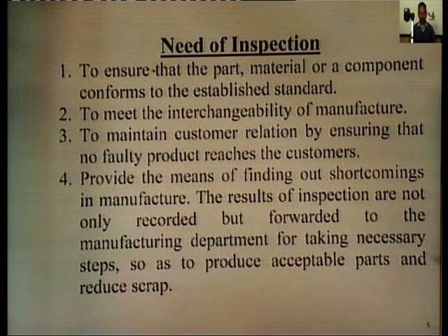Need of inspection. Number one is to ensure that parts, materials or components conform to the established standards. Second, to meet the interchangeability of manufacture. Third, to maintain customer relations by ensuring that no faulty product reaches the customer.